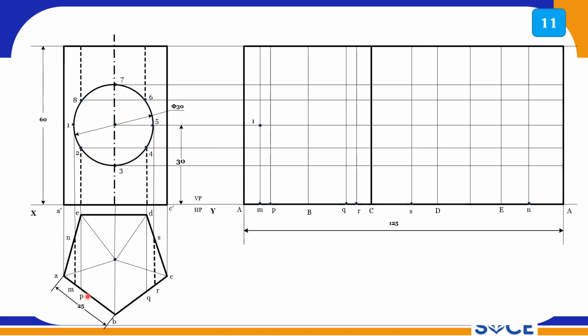And this is on the M line. On the M line you have 1, and it is passing through this surface. On the P line you have 2. It is passing through the front surface, and we are projecting the front side now. So point 2 is on the P line. That's why I have taken these two reference lines, so that I can mark 1 and 2 easily. Now I have 3, there is no problem, it is lying on the B line itself.